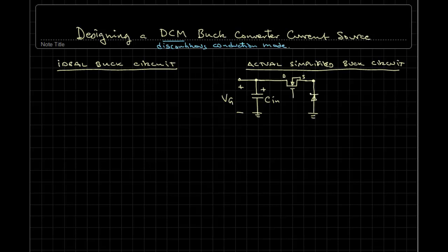If this is a low voltage application, then we probably would use a Schottky diode because it has a lower forward voltage, but those go up only to about 200 volts. And so we have our inductor. This is a power inductor that is designed to handle high frequency, meaning 100 kilohertz, somewhere 1/10 to 10 times 100 kilohertz frequency range, and it handles DC current. Then we'd have some output filter capacitor. I'm drawing just one capacitor, but typically there would be a number of capacitors.